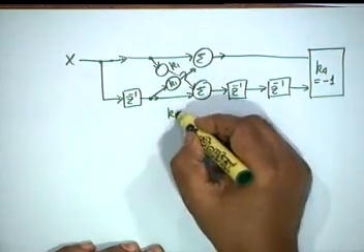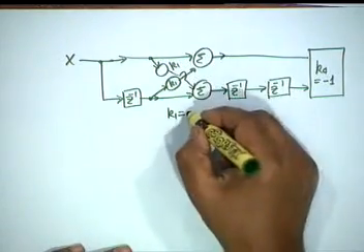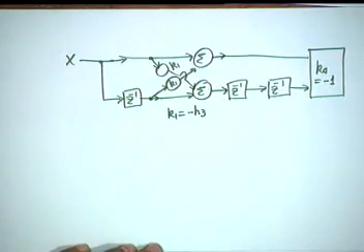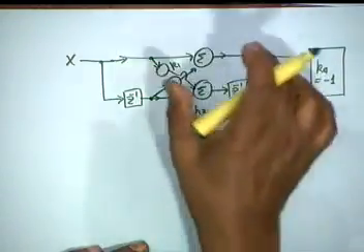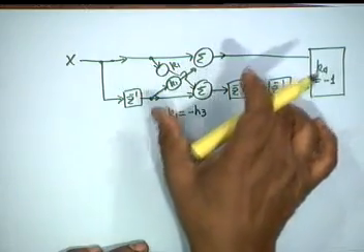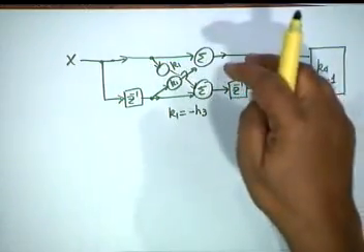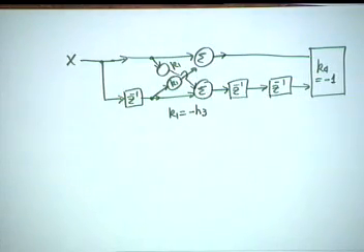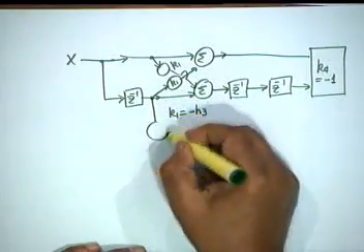Do I know K1? Minus H3, that is correct, minus H3, wonderful. So, everything is done except that we have to take now two tappings. You see, we have synthesized the linear phase transfer function by observation, because from 4 it has dropped to 1 because of the anti-symmetry. If it was symmetry, then from 4 it comes to 2. Okay. So, I have to use two taps.